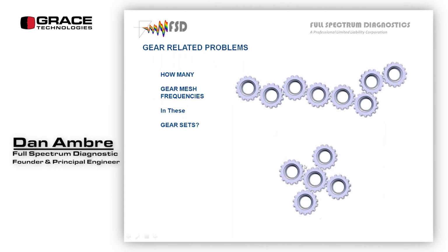Same thing here. It doesn't look real good here, some flaw in the animation, but this is a rotary screw compressor, or lots of different types of compressor with multiple stages. So I have a bull gear in the middle. It's touching each of the pinions. So I only have 1 gear mesh frequency.